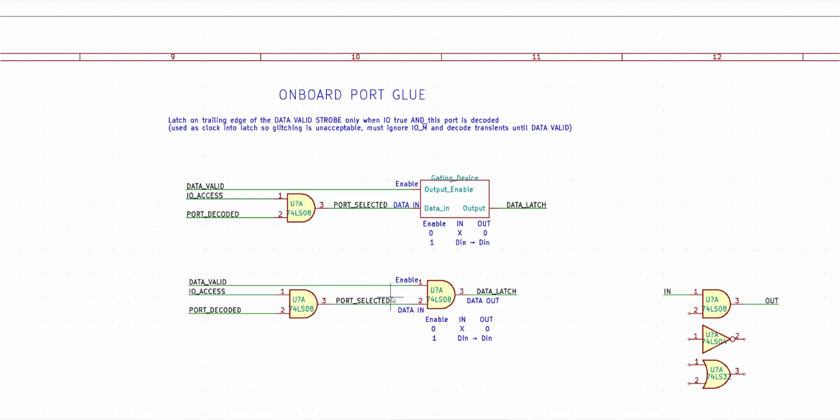My word of advice is this. Look for what I call the superior signal in the circuit. In this case, the superior signal would be the data valid signal, because we don't care what any of the other signals are until the superior signal goes true. Once it goes true, then I only have to work and rework the inferior circuit logic states, so this little AND gate here, since I know they will just pass through the gating device whenever that data valid is true. And if the data valid is not asserted, then nothing's going to get through that gate. It's just going to go to 0.